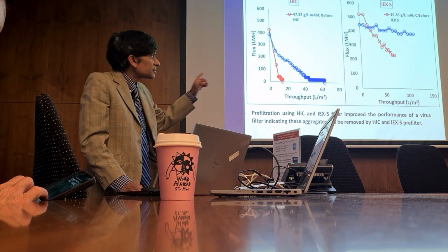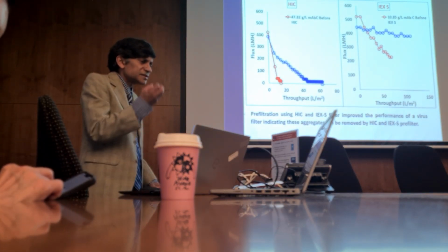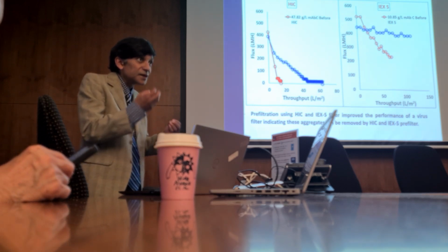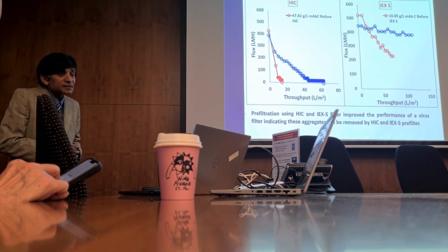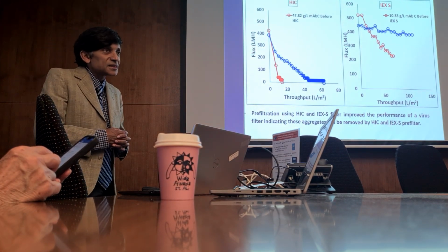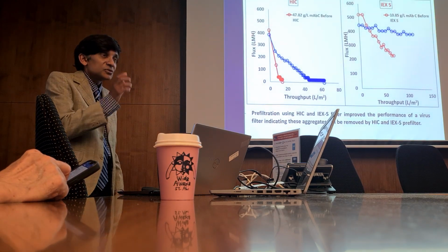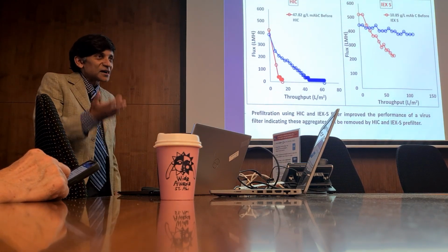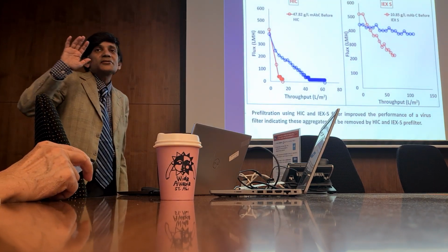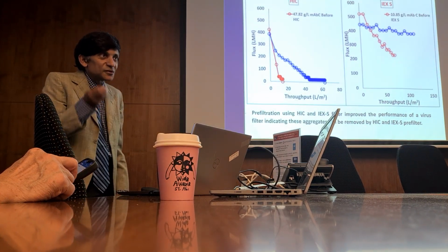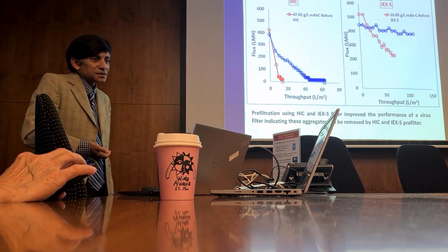Viruses, so I only talked about AAV and lentivirus briefly, and these are so-called non-enveloped viruses. They're fairly rigid, they're strong, so they are relatively not shear sensitive. There are others that are very shear sensitive, and processing them by any sort of flow process like this would be very difficult. If you want to discuss more about viruses used for gene therapy applications, there's a whole range of them, and some are really not practical because they might be very good for delivering your product, but they're not very processable, you see. And so there are many examples of this.